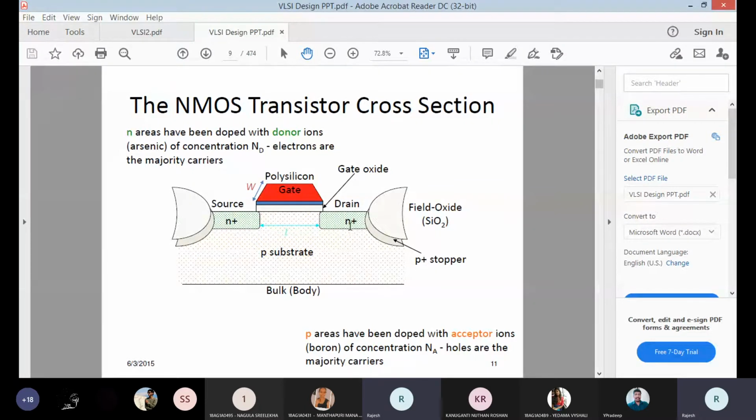Two source and drain regions are formed, as you have seen in the earlier classes, on how fabrication is done to get an N-channel MOSFET into the layers of silicon. So two N plus regions are acting as source and drain. Your oxide is SiO2, polysilicon is metal. So metal, oxide, semiconductor, field effect transistor. Your FET is a voltage controlled device.